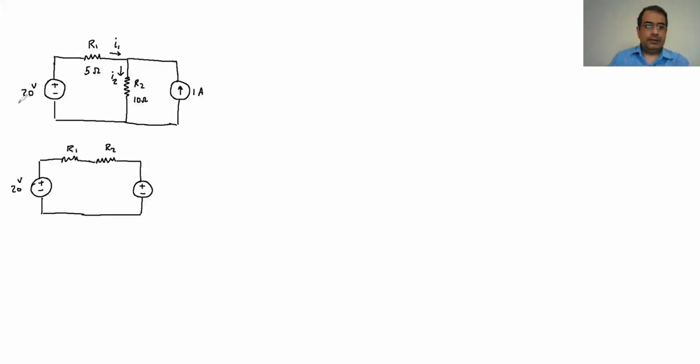Now look at this. I know the R1 is going to be 5 ohm. I already know that. The R2 is going to be 10 ohm, so the R never changed. Now I need the voltage here. For example, I want to know what's going to be the voltage here. So I know the IN. The equation I have is VT divided by RT.